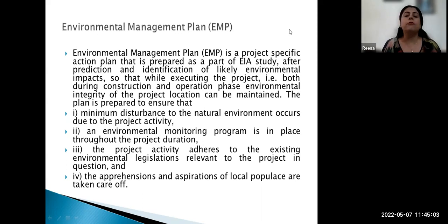a lot of dust emission because of the regular transportation of construction material and movement of trucks and vehicles from the project site. There will be a lot of dust emission, and noise pollution will be there. So what will I do to mitigate during the construction phase? I will ensure that there is regular sprinkling of water on those roads, and if possible, some material should be sprayed on the road so that the surface layer is hardened.